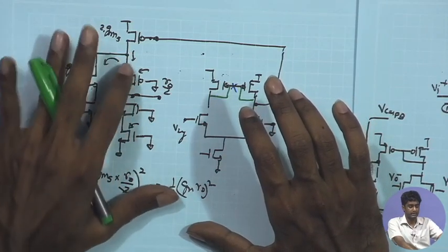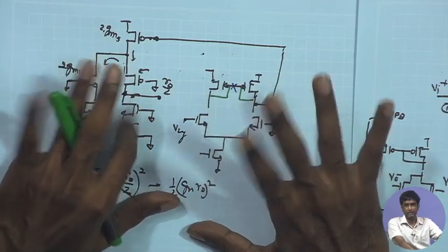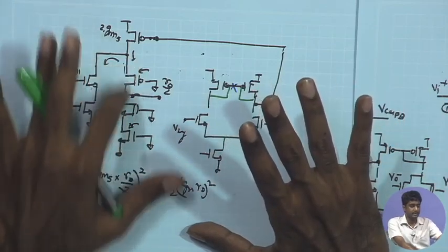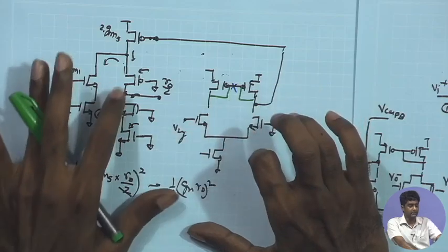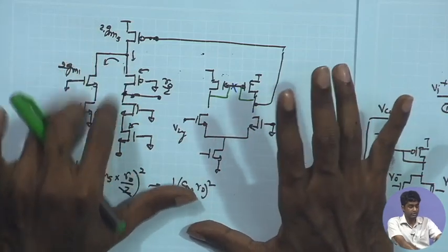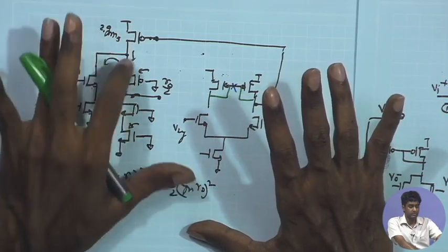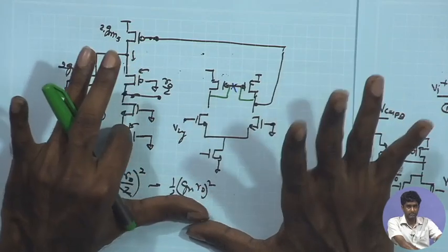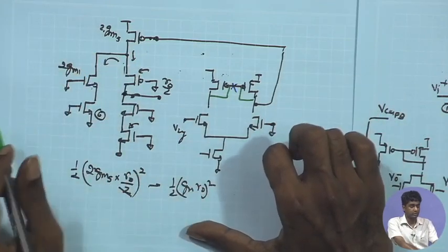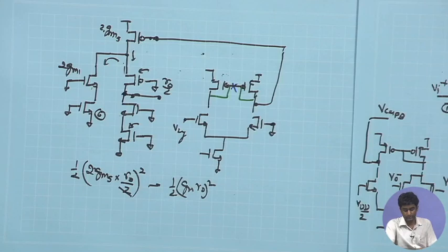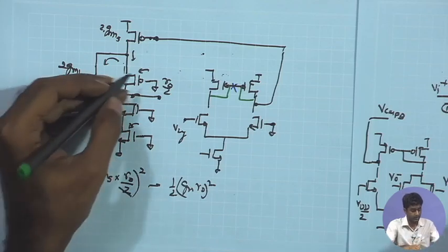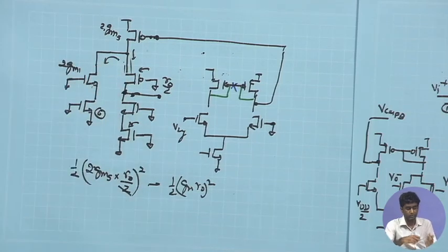We have discussed that the total parasitic capacitance over here can be close to around 100 femtofarad at the max, and for 180 nanometer technology, even if you use larger MOSFETs, the total capacitance over here can be limited to 100 femtofarad. Of course, you have to be careful because some of the devices are going to contribute strongly to the overall capacitance. Which one of these 2 PMOS is going to contribute more to the capacitance?